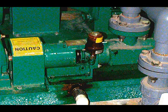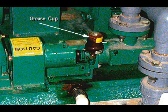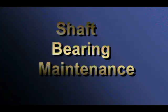Some pumps may be supplied with grease cups. For these pumps, new grease is provided by turning the handle down 1 or 2 turns at regular intervals or by screwing down the cap. The cup is filled with lubricant as required. Regardless of whether the bearing unit is lubricated by oil or grease, there are some basic operational checks required regularly.